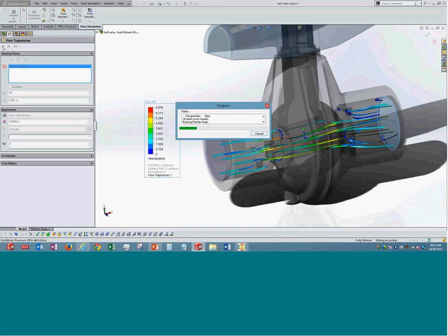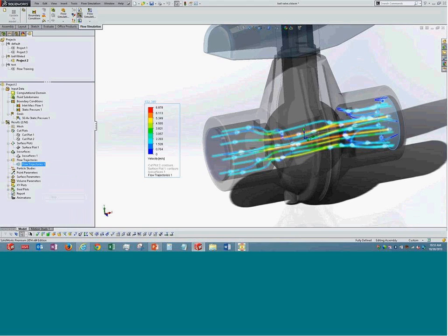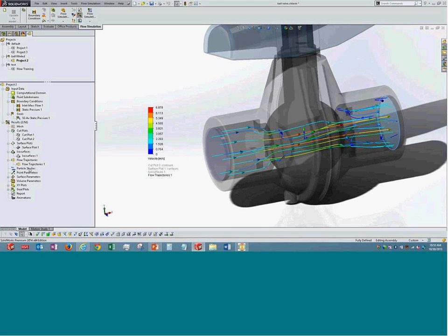Other, if you are interested, we can do a particle study. We can insert a certain number of particles at the inlet, and we see whether they go out of the system or they settle down in the system. And we have surface parameters. We can do some measurement of the quantity that is of interest. I told you it could be forces or torque, etc. If I click that and show you, it is zero here, but it could be the pressure on that particular surface. It is of this value.